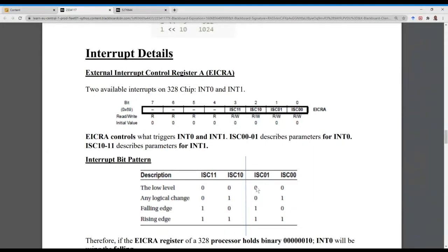If you are using pin 2 only, then 0 0 in this particular register means that your interrupt will respond to the low level. Now I'm going to make this clear to you. You are to use different interrupts also to show that different people have different sets of code, which means you really want to use something different in here.